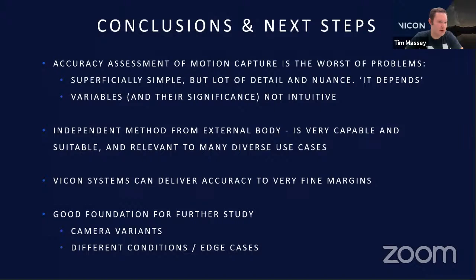There is a very interesting study that the ASTM themselves did, where they looked at the movement of a wall with a laser measurement system in a building that cameras were mounted to. So nothing to do with the mounting of the cameras themselves, just the structure it was mounted on and how that changed. One of the findings was that an internal wall in the same volume, due to the temperature changes outside the building, moved or fluctuated a lot less than an external wall.